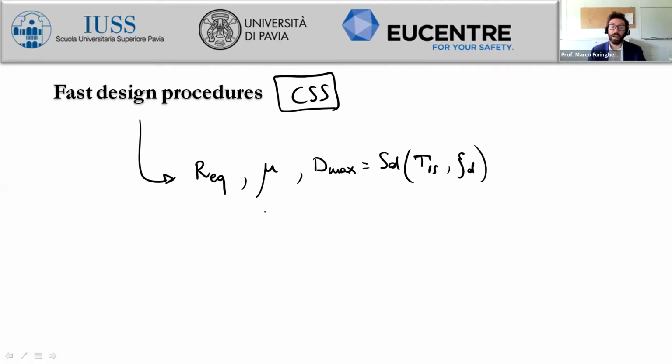We have also the normalized force response, but this parameter could not be addressed to some geometrical characteristic. The maximum displacement, however, can be addressed to the geometry of the sliding device, because we have to design the lateral geometry, the horizontal geometry of the sliding surfaces. So we have to allow that displacement, and this is a useful piece of information for the overall geometry of the isolator. Let's consider these parameters one by one.